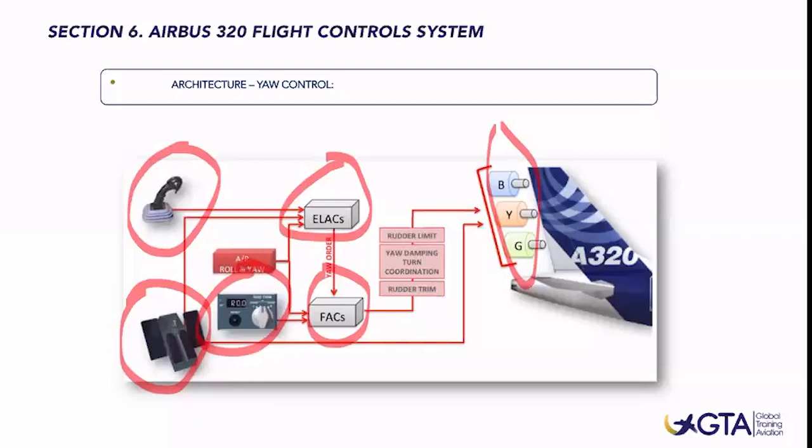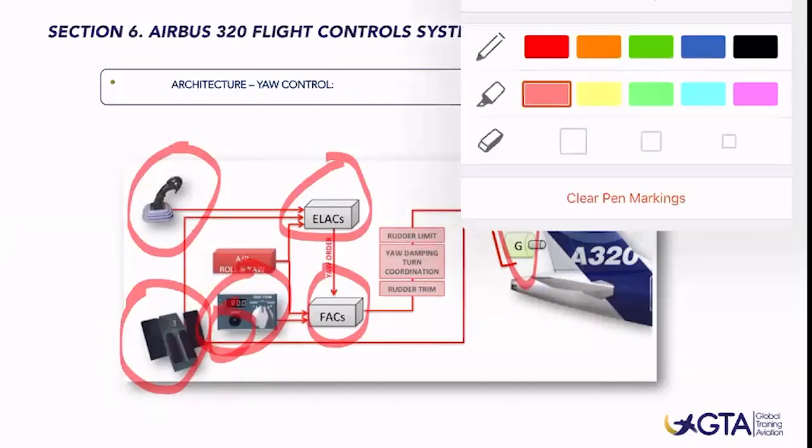Well, additionally, in the same rudder trim panel, we have the reset push button, which we usually use on ground just to reset this rudder trim position. As soon as you press this reset push button, the rudder surface will swap into the neutral, to the 0 degrees deflection.